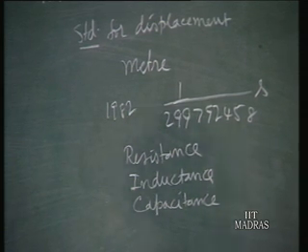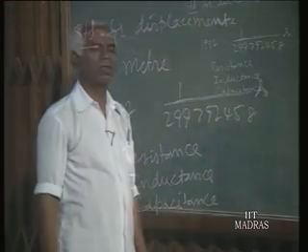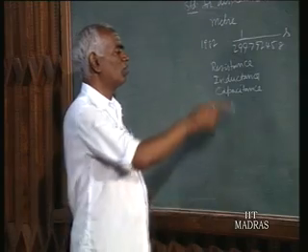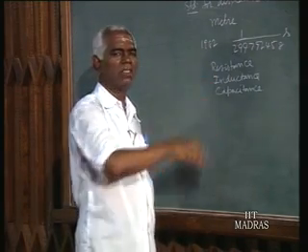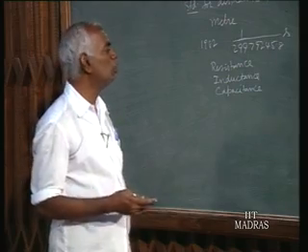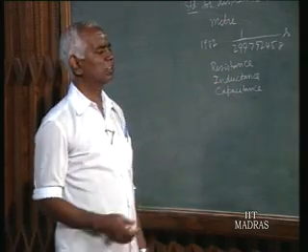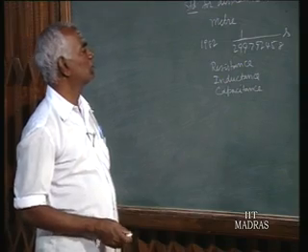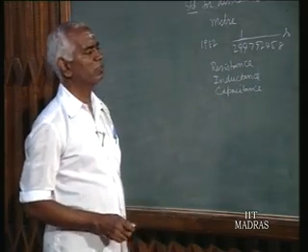They are used. The distance you want to measure is used to make some variation in resistance, or in inductance, or in capacitance, and these elements form part of an electrical circuit, and there you will get a voltage output. This is the basis or concept of making displacement measurement by using these passive elements.